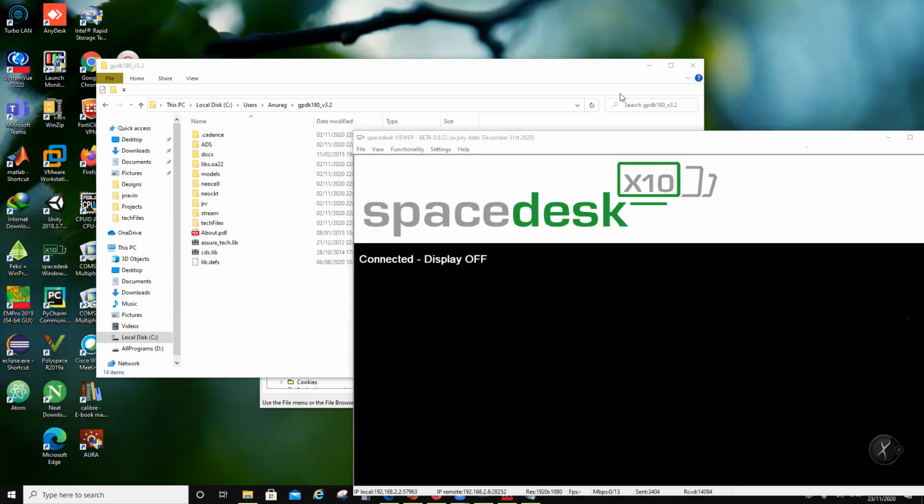Now, different tools are trying to attempt the same stuff. For example, ADS has a method of moments or FEM, or let's say EMPro. It will allow you to do EM simulation in their tool, bring those results into a circuit simulator like HB or transient, and then do a co-simulation, right? Same thing with Cadence. Cadence has an EM simulator. You will be able to simulate an inductor, but then you will be running a circuit simulation with a text file as an input for your S-parameters. So there is no confusion here.